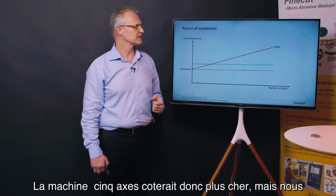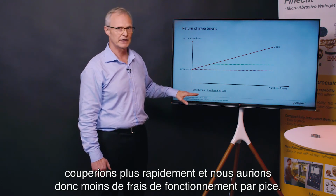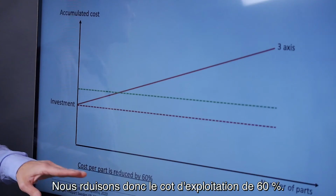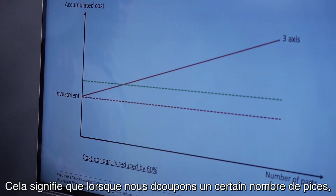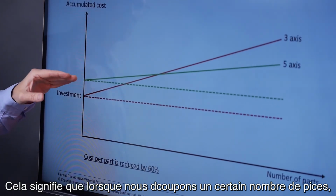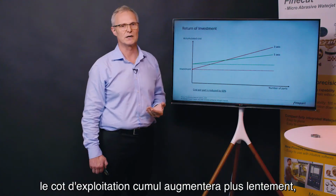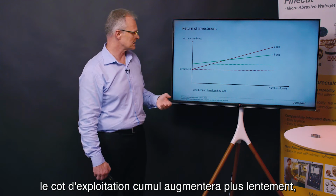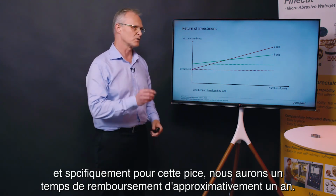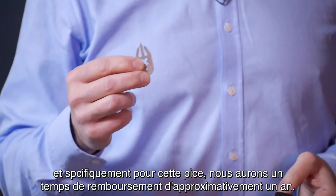So the 5-axis machine would cost more, but we cut quicker, so we will have less running cost for each part. So we actually reduce the running cost by 60%. And this means that when we are cutting a number of parts, the accumulated running cost will increase more slowly. And for this specific part, we will have a payoff time that is approximately 1 year.